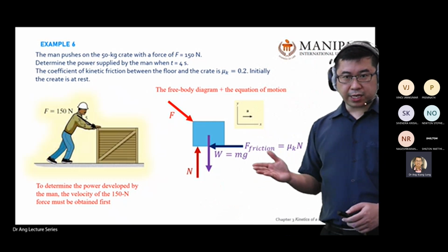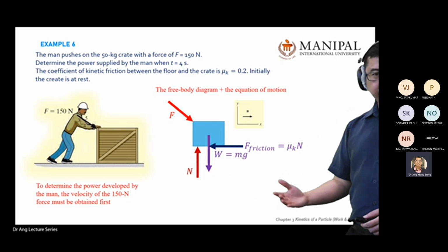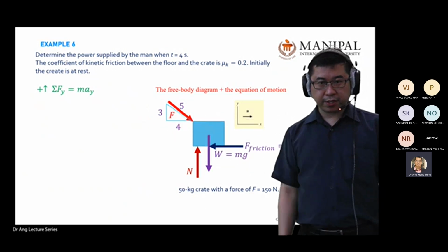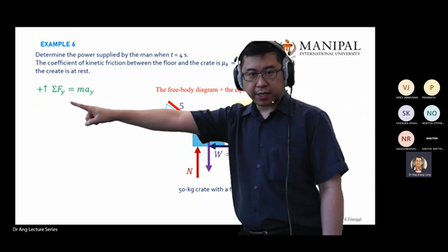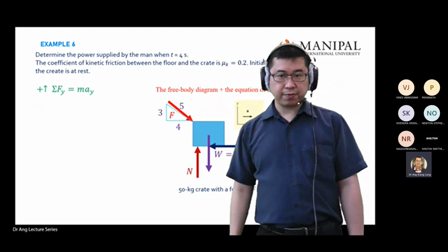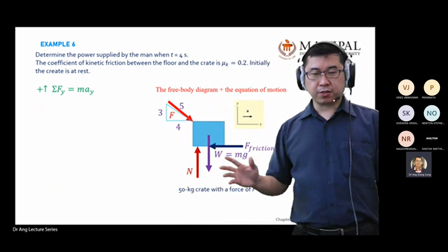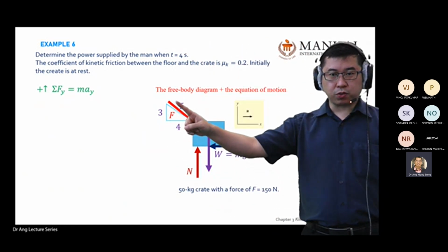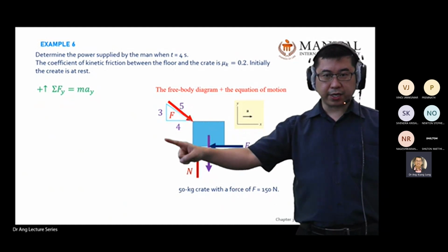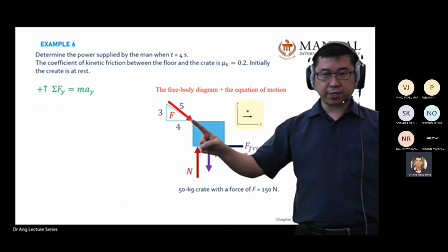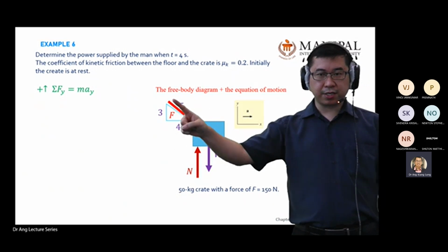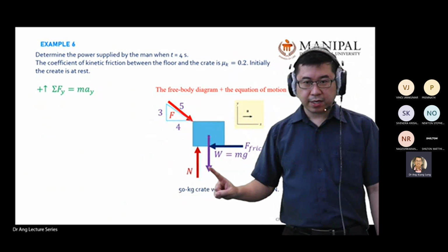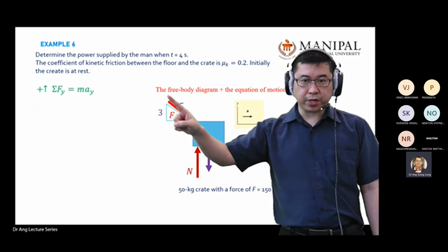Okay. So let's move on. The free body diagram already explained how you get it. Next, you solve the equation of motion. F equals ma. In the y direction, going up is positive. You focus on the y direction forces. This one you can split into two components here and here. The resultant force you can change into this direction and this direction. So you're focusing on y, you have this one, you have this one, and one component going down, which is negative.